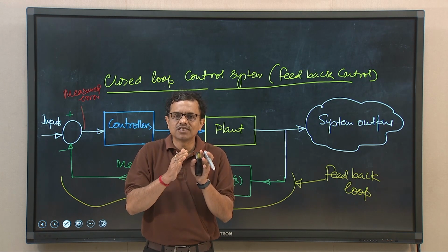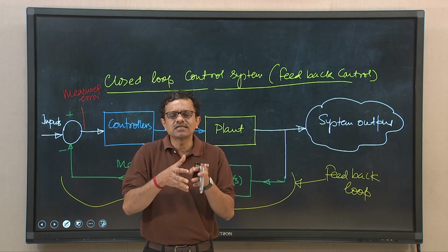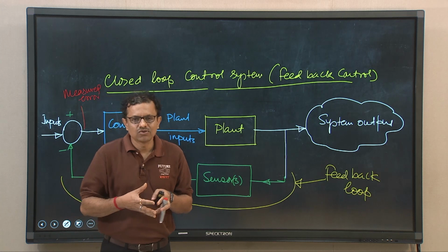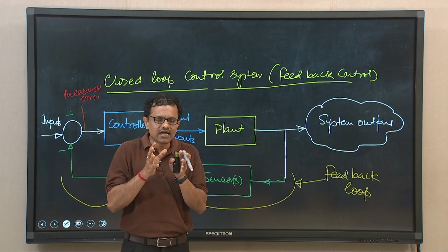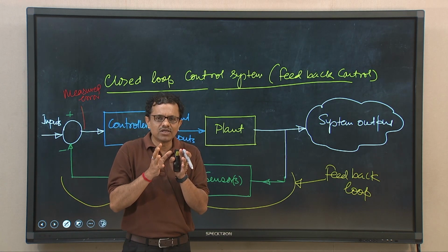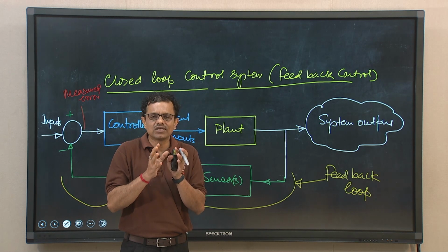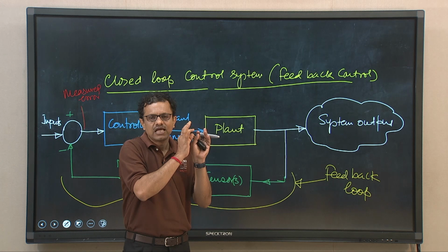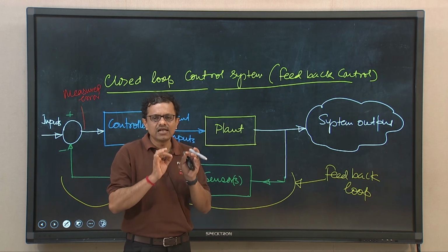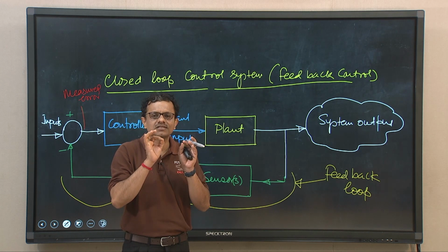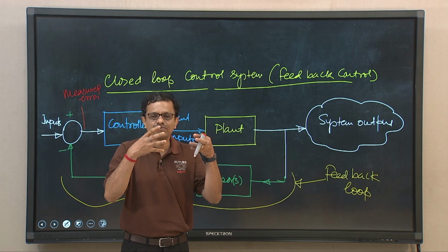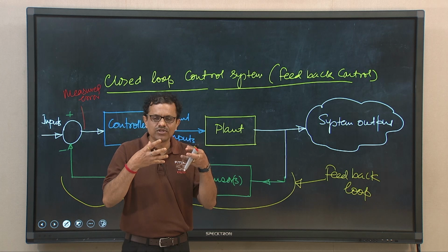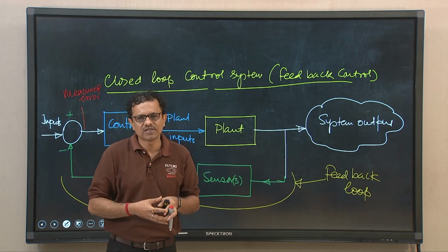So, combustion was improper and excess oxygen comes out with the combustion gases. Then the ECU, or engine management system, will give an output signal to the fuel injector asking it to supply more fuel, so that the excess air can be combusted with the additional fuel supplied.